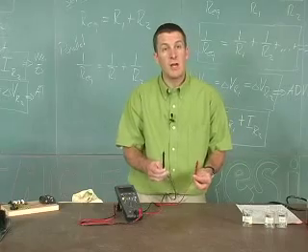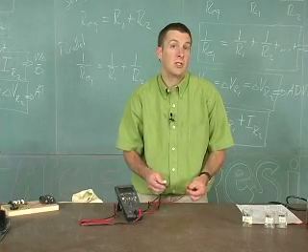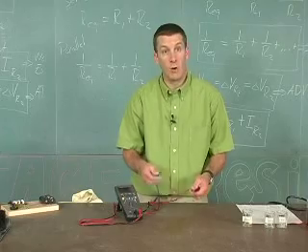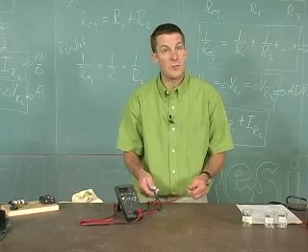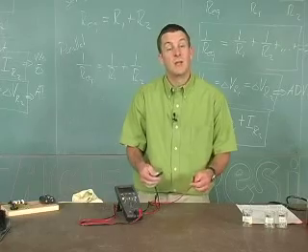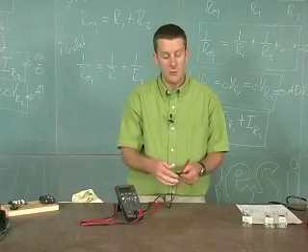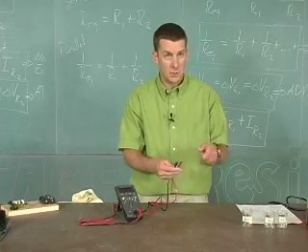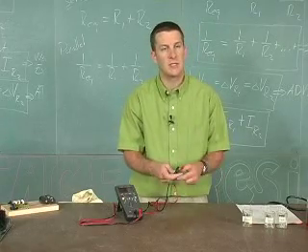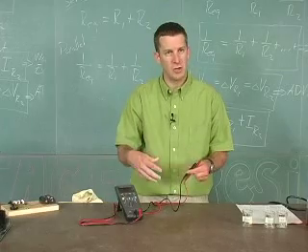You can measure voltage across an element. Remember, it's just considering the difference between one end and the other, and the voltage doesn't have to flow through the device. Same thing with resistance. There's a battery inside here that if you touch the two probes to any conductor, it will measure the resistance by pushing a small current through that object and measure it.